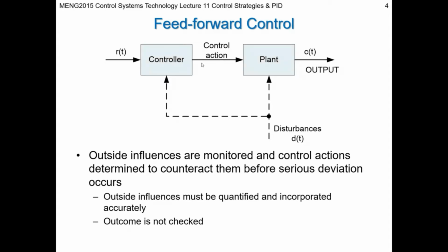And there are a lot of benefits to feed forward types of control systems. The main one is that they can react faster. So rather than waiting for an output from a system to vary from its set point, you're preemptively correcting for things that are going to affect the output state. That allows the system to respond more quickly than it would if it was waiting for the plant to change its state, for the output to change, before it then corrects it.